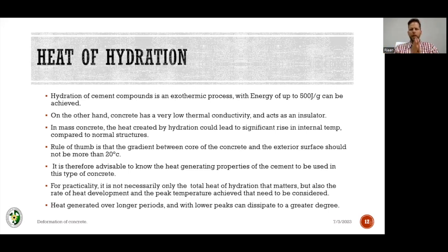This is where your C3A and your gypsum has already reacted. It's formed ettringite, and now this ettringite is covering everything. The inside of the drum, it's covering the aggregate, it's covering that rubber glove that by mistake went into the concrete also. It's covering everything. And this ettringite, now this process stops, and the ettringite is there for 1.5 to maybe 3 hours, delaying the actual hydration of your concrete. So no more heat gets built up. Your drum can now slowly run, and the heat gets dissipated to the atmosphere.